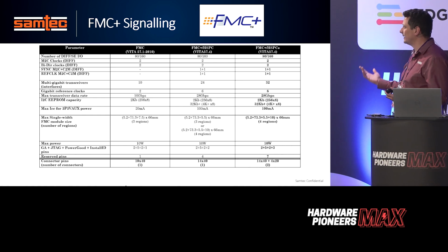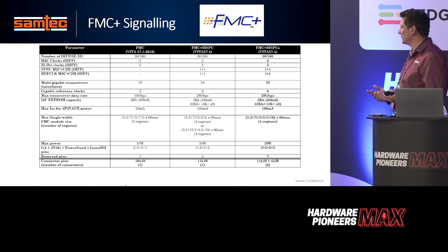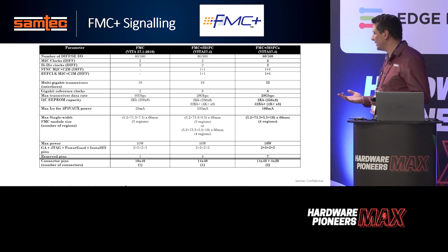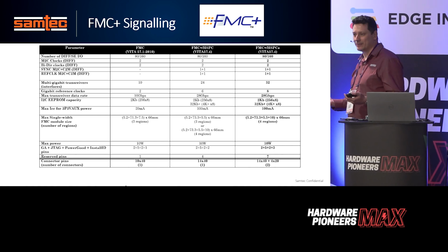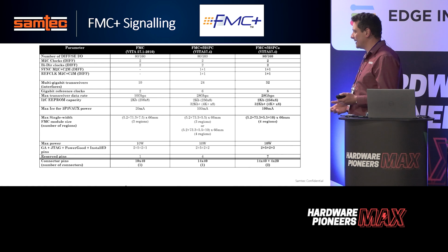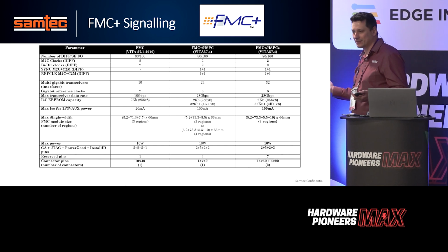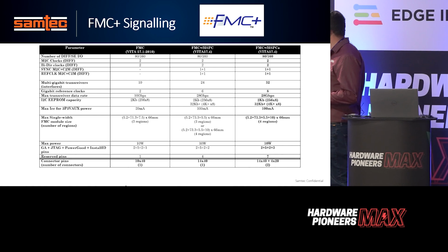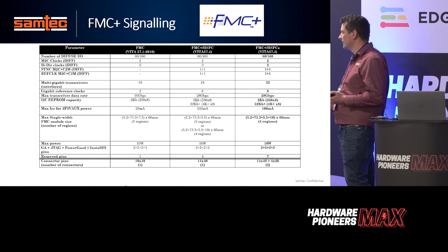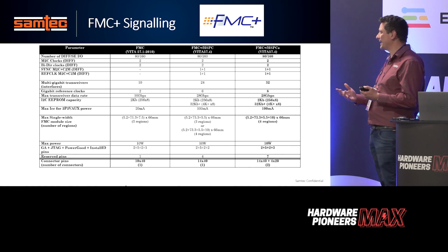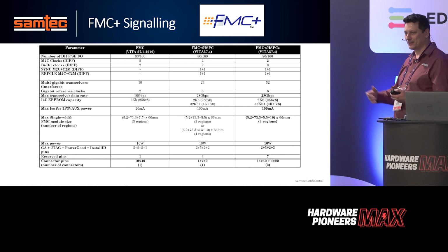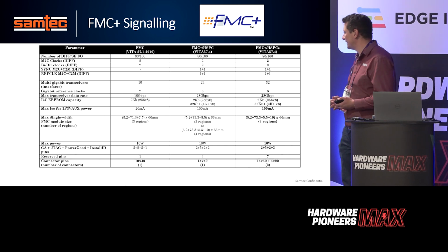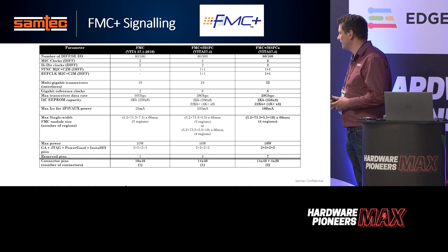When we released SEARAY, even before 2010, 10 gigabits was not really typical. There were not many SerDes available at 10 gigabits. Now we see SerDes up to 112 and even 224 gigabits. So the connector is exactly the same, the standard changes, and now it's written up to 28 gigabits. So many people ask me, okay, can I use an FMC mated set for 28 gigabits? The answer is yes. You can do it. Obviously, look after the design into the PCB, but you can do it.